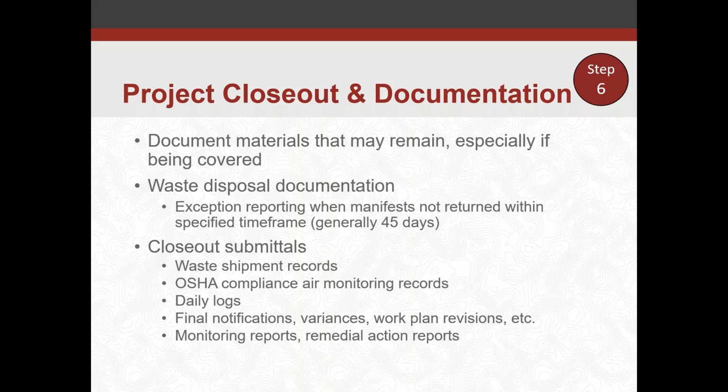Step 6, the next step, we're looking at project closeout and documentation. So document materials that may remain. Especially if you're covering material, doing some sort of enclosure, you want to document where that material is enclosed so that nobody just goes and rips into that wall or ceiling or whatever it's enclosed with and finds it unexpectedly. You want people to know that if we're going to do work there, we really have to do it under abatement conditions because of what's behind it.